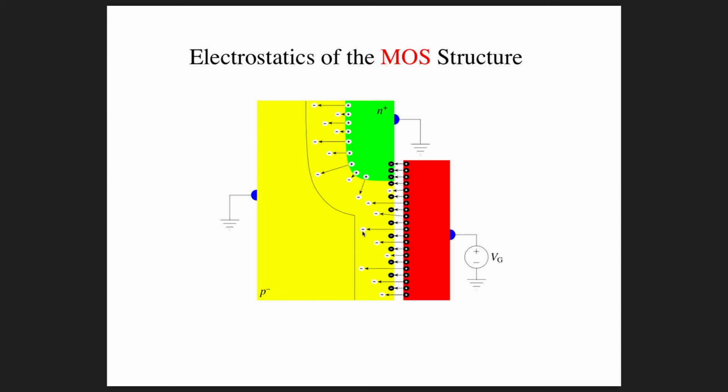So this voltage on the gate at which this condition occurs, where we get these equal width depletion regions, is called the threshold voltage, which we denote by VT. We use UT for the thermal voltage and VT for the threshold voltage. That's why we use U for the thermal voltage, to distinguish it from the threshold voltage when we get to MOSFETs, in case you're curious about that.